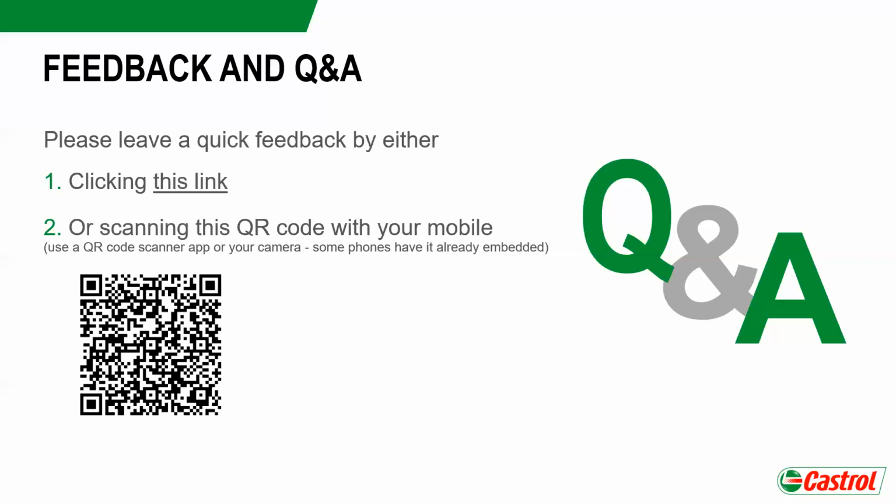Phil, you wanted to add something? Thank you, Marcus. Yeah, I think you've pretty much covered that. To add from a practical perspective as well, how would you measure energy saving if you have so many variables? If you take good baseline readings, which could be, if it's a three-phase motor for example, readings of your current draw over a certain time period to cover seasonal variations too. Also, temperature readings of the gearbox. You would expect that if there's friction, metal against metal, the temperature would rise. And we have seen this.